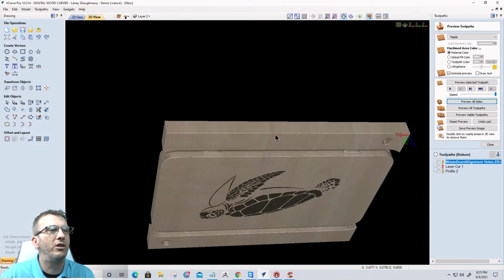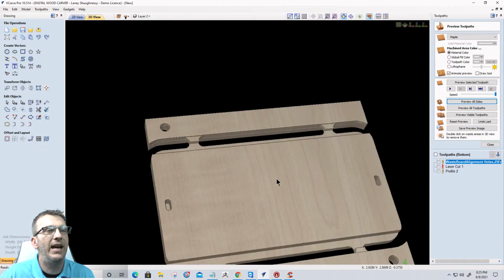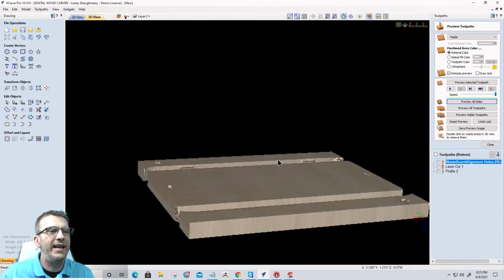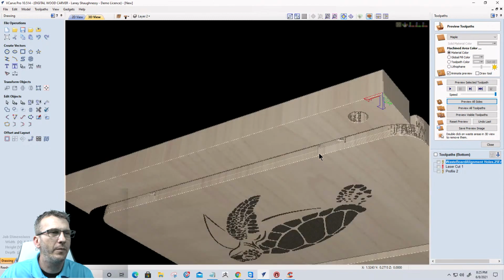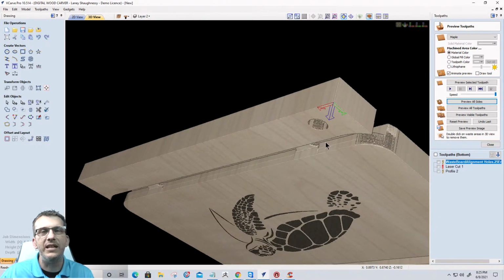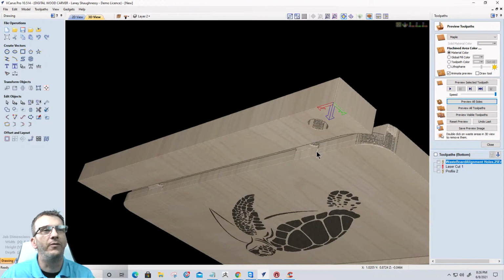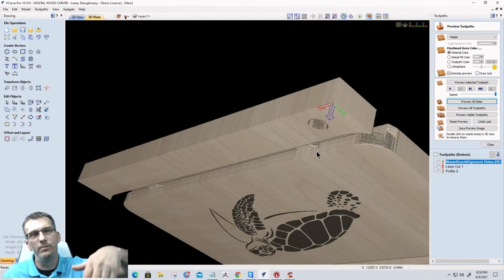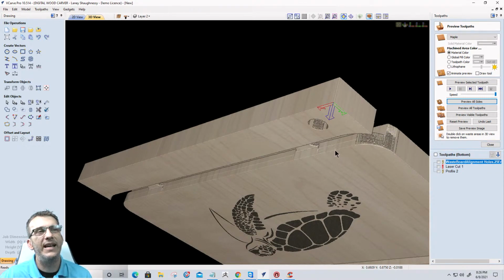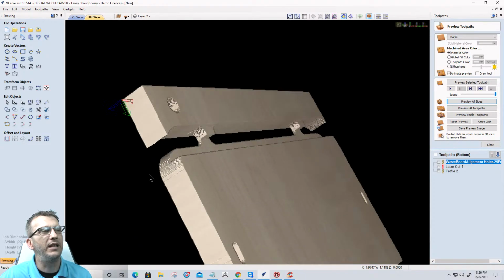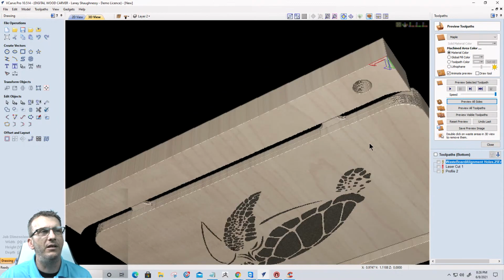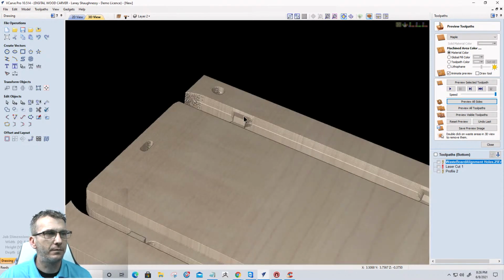That looks good. If I wanted to be more secure, then from the bottom side I would do a profile cut. That would be the final side that I cut. I'd do all my laser engraving or inlay work first, and then I'd come to the bottom side and do a profile cut all the way through, so that my tab has, let me see if I can get to that angle, this lower meat here, because the tab starts at the bottom of the cut on that profile cut. At the bottom of the material, the tab starts from the bottom up, right? So I have all this meat here. If I just did a single pass all the way through on side two, my bottom side, then I could put my tabs down there. But by cutting half and half, part of my tabs are getting cut away. And I'm okay with that because there's still plenty of tab there to secure that.